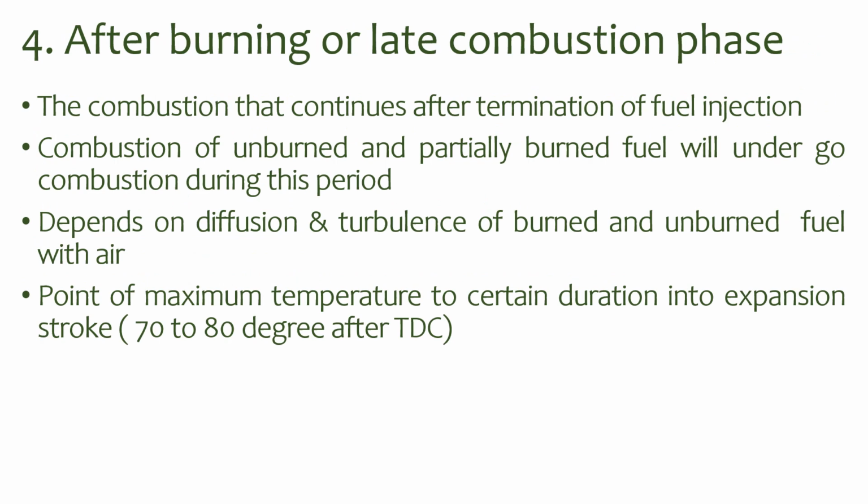The last stage is afterburning or late combustion phase. This is the combustion that continues after termination of fuel injection. The unburned and partially burned fuel will undergo combustion during this period. The afterburning depends on diffusion and turbulence of burned and unburned fuel with air. The afterburning lasts from the point of maximum temperature to a certain duration into the expansion stroke. It's around 70 to 80 degrees after top dead center.